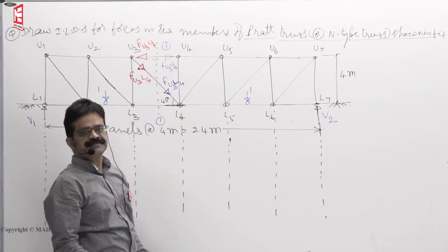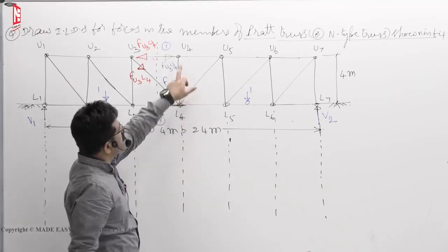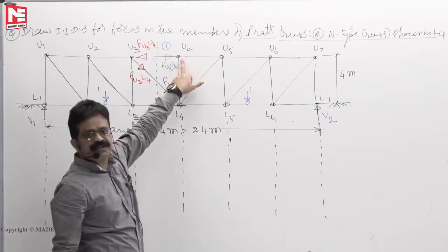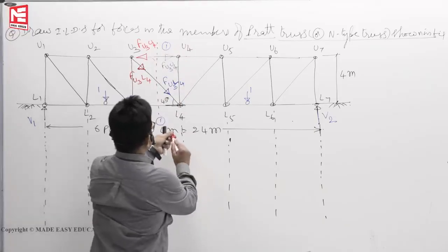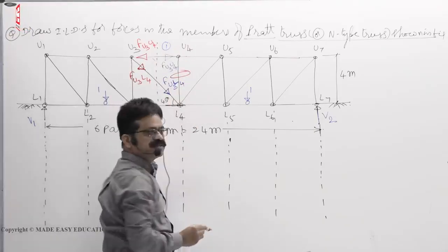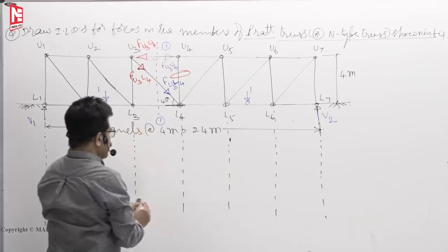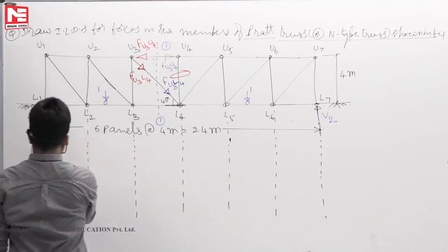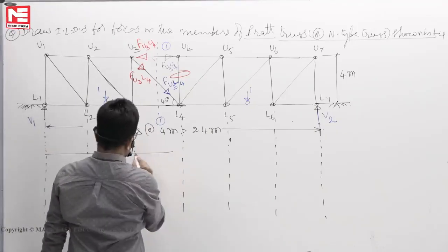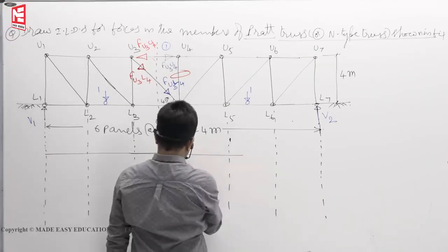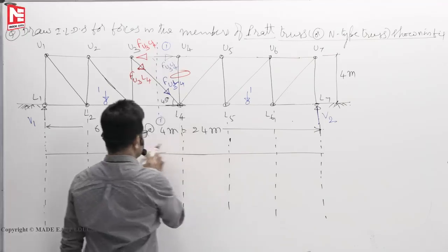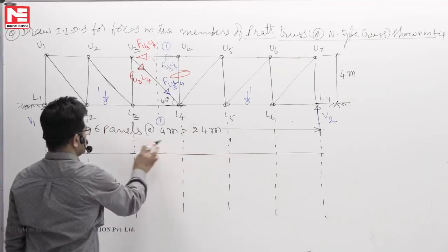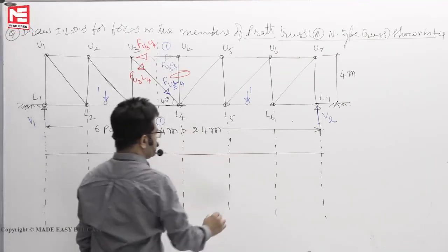Again problem. So, you see the member configuration at the joint U4. Of the three members, 2 are in line. So, the force in the third member is always 0. So, the ILD is simply a straight line you will get for this one, telling you that for all positions of the moving load, the force in the member U4L4 is 0.